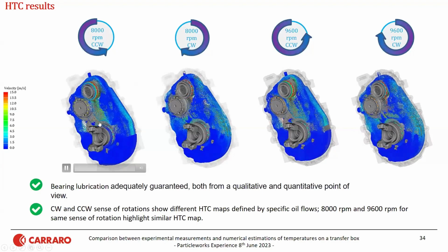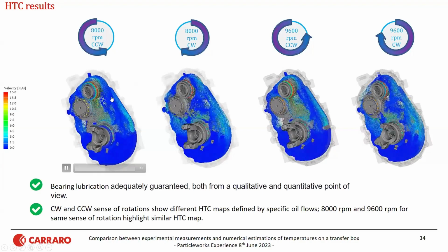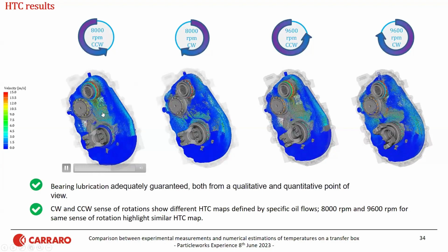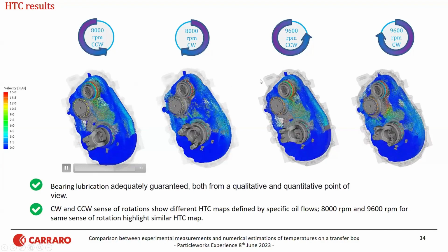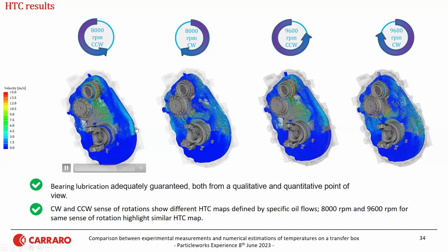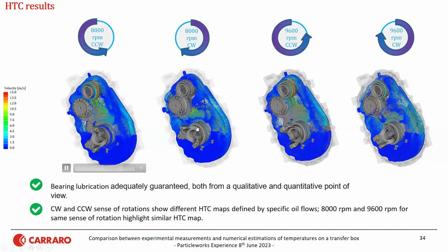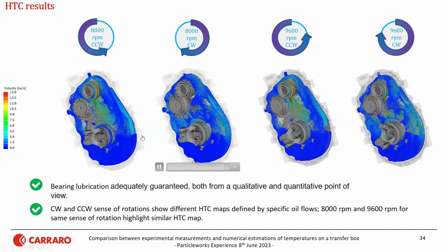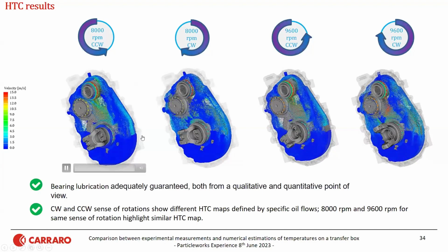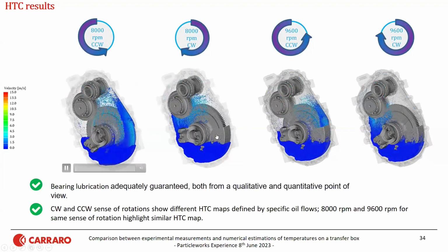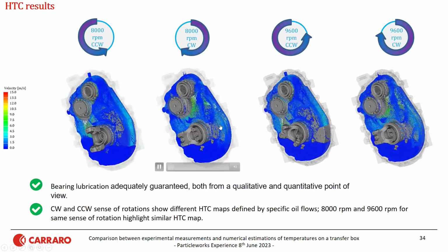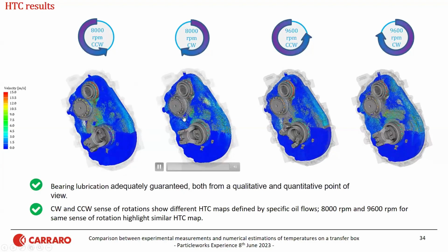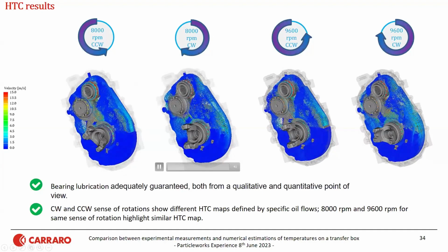So of course, the first output of the simulation is usually to visualize the flow, to understand the churning losses, or understand if the bearings are well lubricated, for instance. Okay, so compare this kind of configuration. So the standard output are those ones. You could also maybe just change a baffle, change some geometrics of the system very easily, and understand how that impacts the